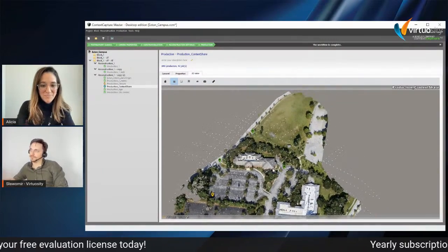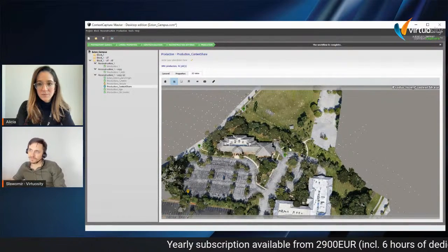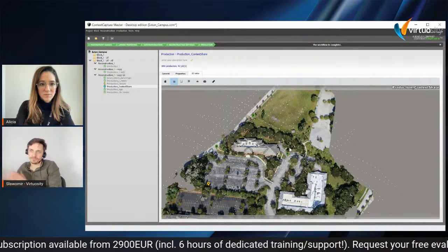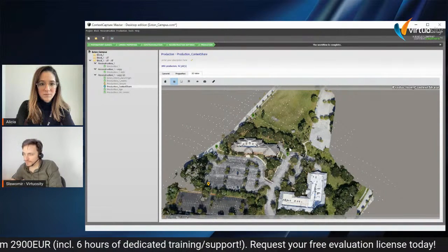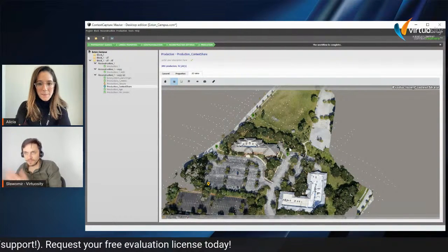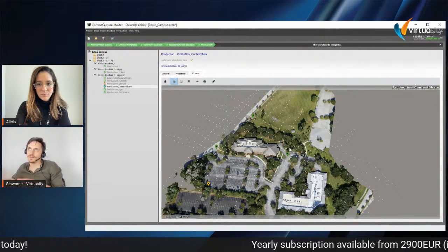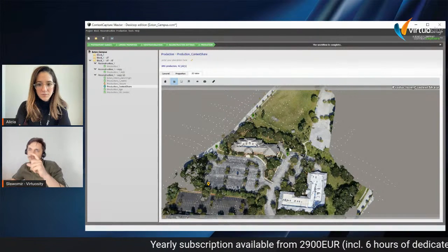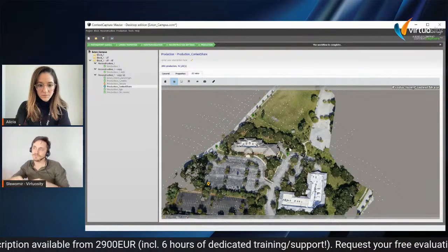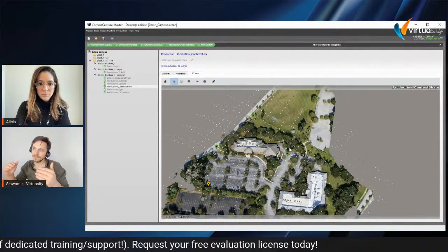Yes, exactly. In ContextCapture Editor, we have tools for ground extraction. What it does is extract single z values and convert the mesh to a form where you won't find two elevation points above the same xy coordinate. So there is no chance for, for example, a tunnel or some bridge. Of course, but also there will be no noise.